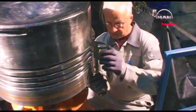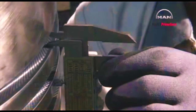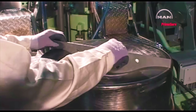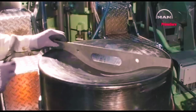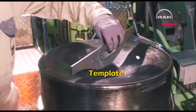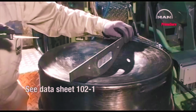Check the ring grooves. The maximum vertical height in a worn ring groove must not exceed the value stated in the datasheet. Check the burn-away by means of the template. The maximum permissible burn-away value, see datasheet 1021.